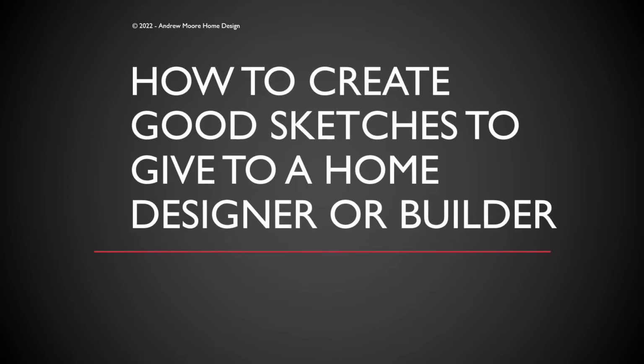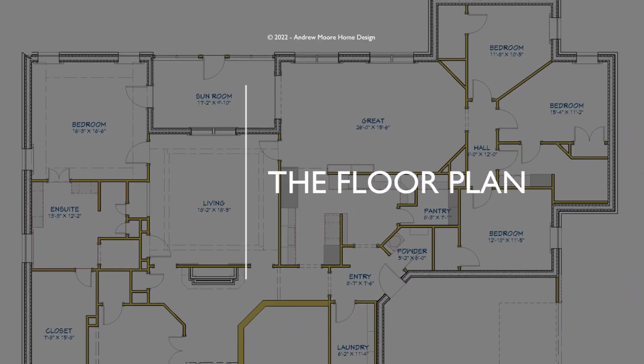The most important drawing in any house plan is the floor plan, and that is where the process of designing a home normally begins. In fact, one could argue that the floor plan dictates all of the other drawings in a plan set. For example, roof lines, door and window locations and their sizes, the outlines for the foundation plan, etc. The floor plan is also used to create the electrical plans, plumbing plans, etc.